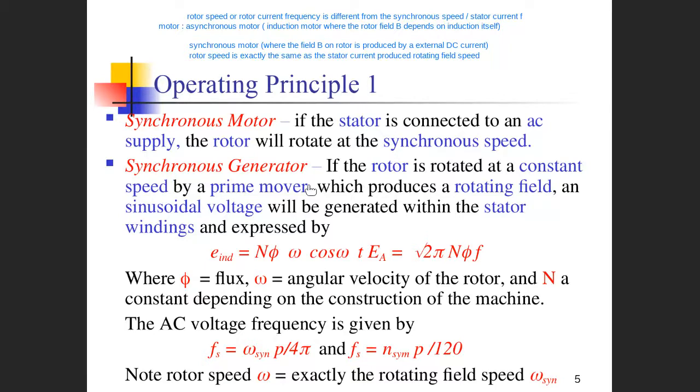If the rotation speed of the generator is unstable, and the magnetic field is unstable, then the frequency of the generated electricity is unstable. That's terrible. So that's why we really try to keep the generator synchronized.